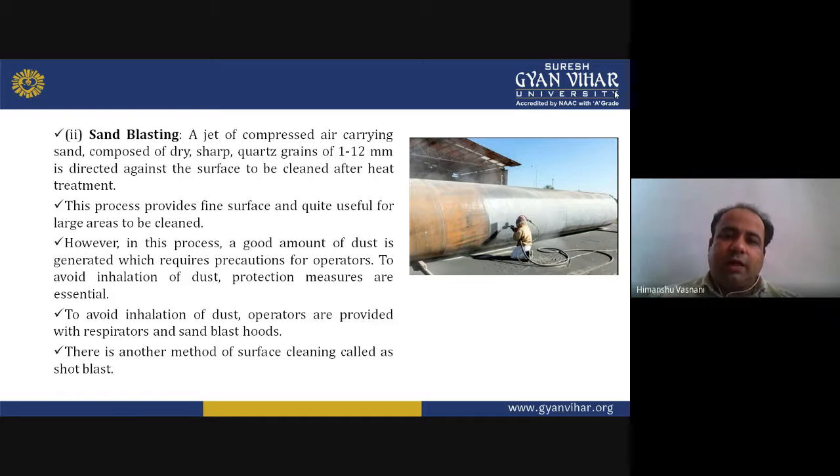To avoid inhalation of dust, protective measures are essential. As you can see in the diagram, the operator is wearing a helmet to protect himself from the dust in the atmosphere. Operators are provided with respirators and sand blast hoods.